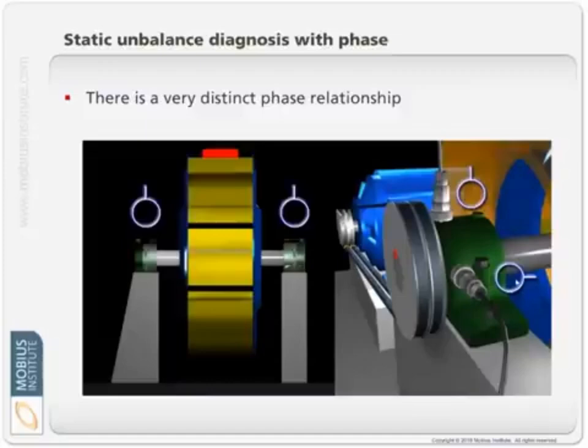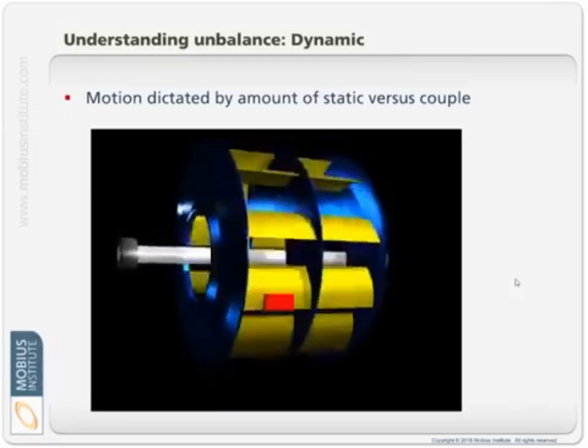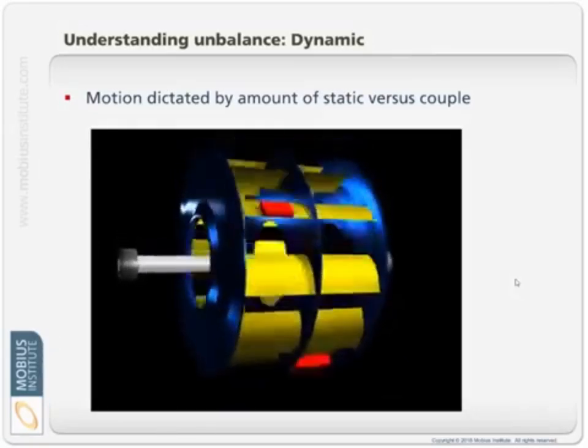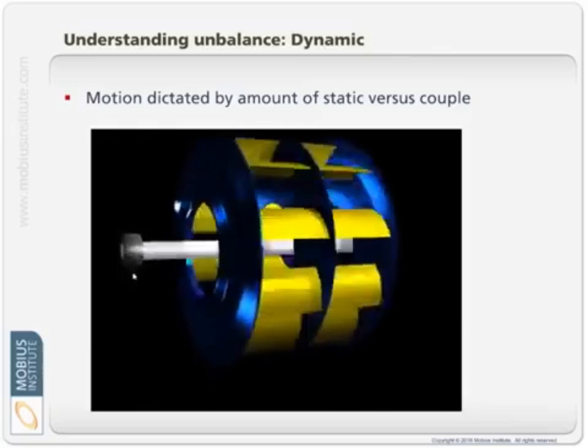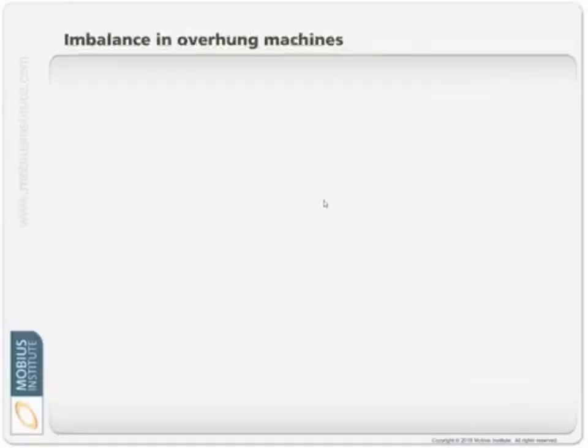Okay, I'm not trying to teach you vibration analysis, just show you that these measurements can be put to good use. This is a more complicated situation where we have a longer rotor out of balance, but actually this bearing is still moving in a circular motion. It's just that from one end to the other, it's not either perfectly in phase or perfectly out of phase. It tells us how severe the problem is, though. It tells us how we need to go about balancing this machine.